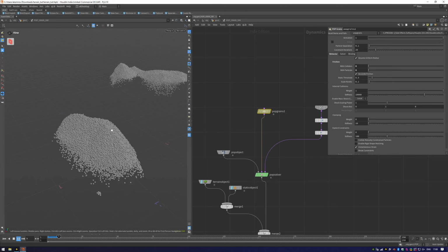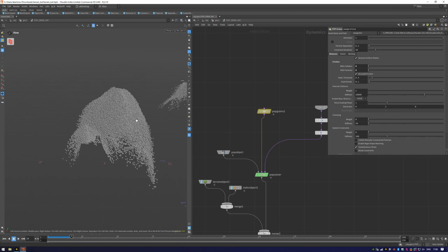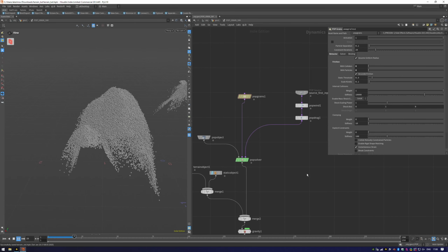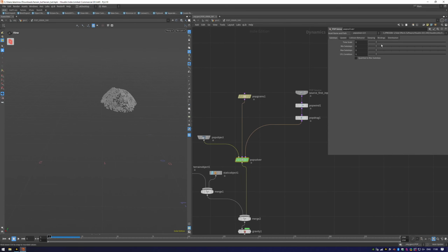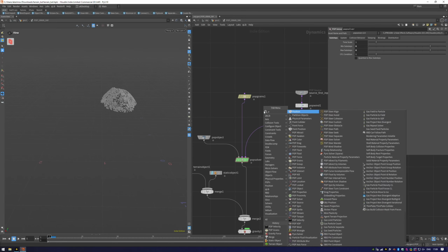And if you hit play, you can see they got some interaction, but if you turn off this real-time playback, it's very jittery. In my case I used 8 sub-steps here. You can go a little bit lower, but I just used 8. It's going to be a lot slower, of course, as you can see here, but you're going to get a nicer, smoother result.